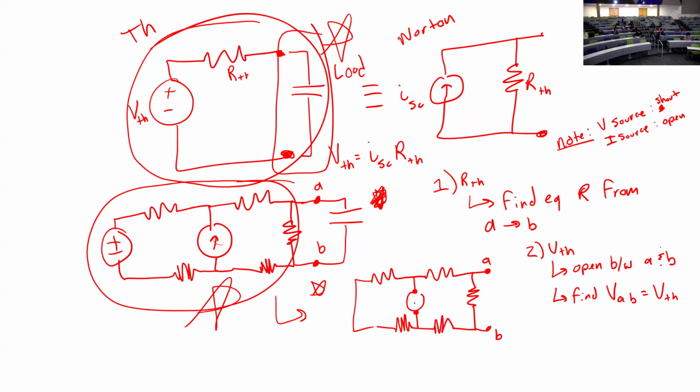So in this circuit I've talked about before, if we go back to having my current and voltage source, okay? Now when I solve this, I'm looking for whatever this voltage is, from here to here. All right, that's how you'd solve V Thevenin in this case. You're solving for that voltage there. Whether that be node analysis, mesh analysis, any kind of combination of those processes, you need to be able to end with finding that voltage there.